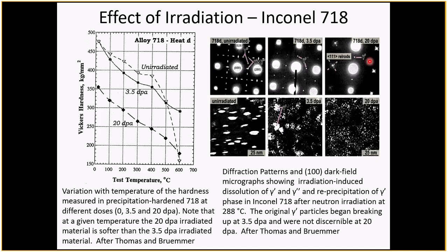So radiation damage may be dispersing and mixing up the material just simply by ballistic mixing. At the same time, you've got the thermodynamics acting and the material wants to reorder. So you'll get to some minimum point where the two processes are balancing one another. So you end up with a little bit of gamma prime after a high dose.